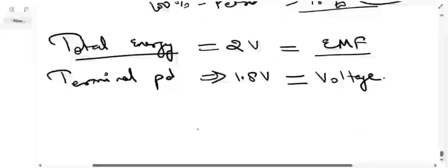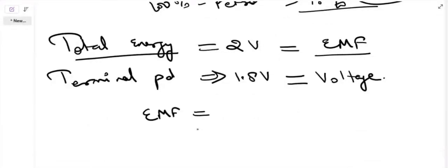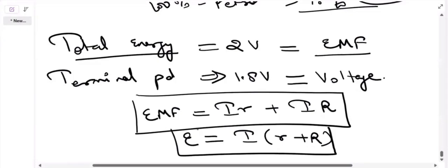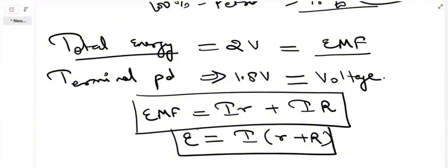Now this is known as the voltage of the circuit. So when you are calculating the total EMF of the circuit, you need to add the voltage drop across the battery's internal resistance as well as across the external resistance. Now you will get the complete EMF of the circuit. Making sense? Yes, ma'am. So the formula is EMF equals V plus Ir. It's very, very important, and many times it comes in the exam. Any doubts? No, ma'am. Okay.